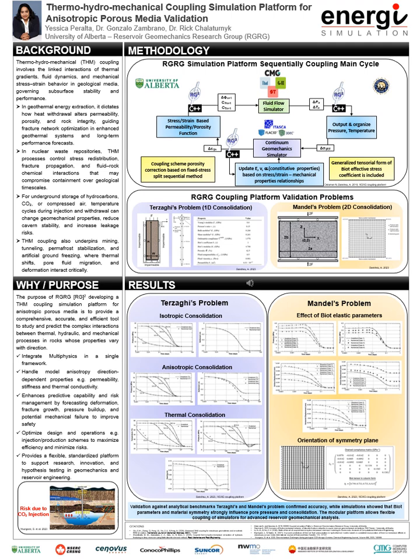For our simulation, we discretize the layer into small cubic elements, as you can see in the picture of the geometry. The rigid plateaus are modeled using a servo control mechanism which adjusts the vertical velocities at the top and at the bottom boundaries to maintain a constant applied load. Fluid drainage is allowed through wells along the lateral boundaries.